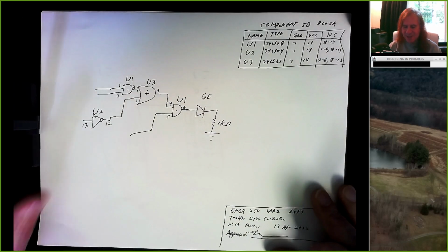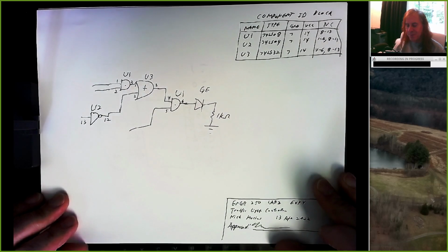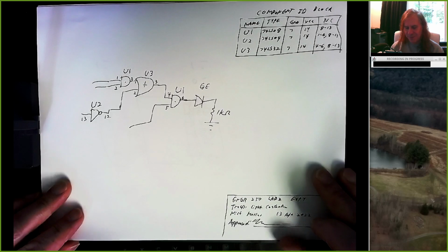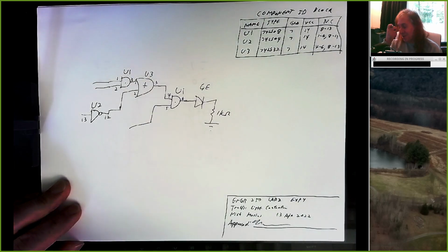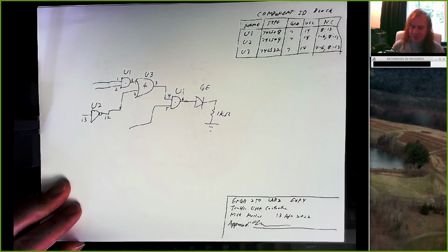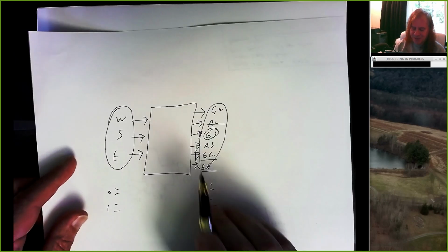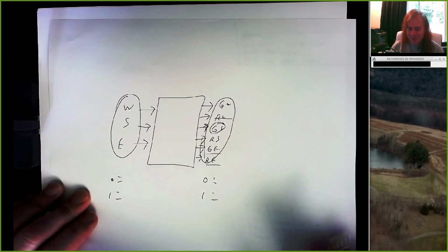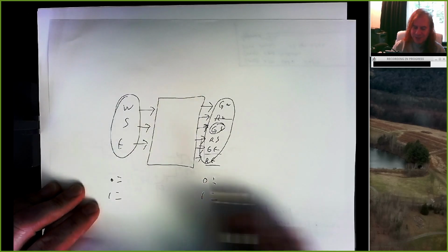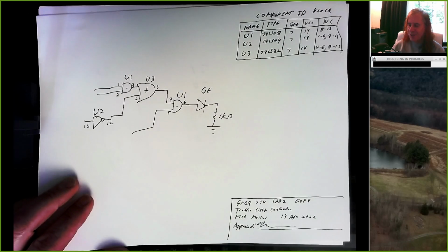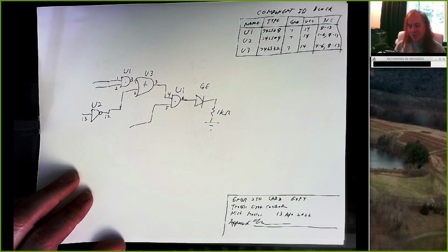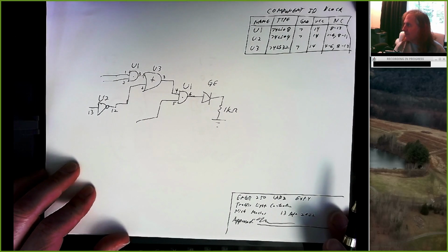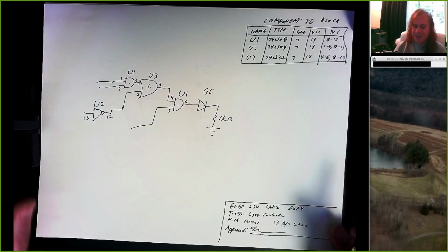Imagine that you're in a factory and somebody's going to build 1 million of these units, and you might label this east, or east comma green or something. If it doesn't match this, there's an inconsistency. So whatever labels you use for your outputs and your inputs in your system diagram, those should be the column headings in your truth table, and those should be the LEDs and the switches in your schematic. So all of the stuff should hang together.